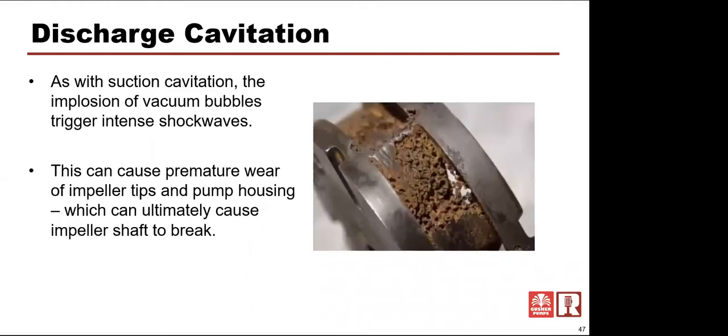When you look at an impeller, it's going to have a different appearance because a lot of that turbulence is happening out there by that cutwater and out at the vane tips of that impeller. A lot of that cavitation is going to happen right near the tips of the impeller vanes on the pressure side now, because that's where it's trying to feed back across to go to the low pressure side.